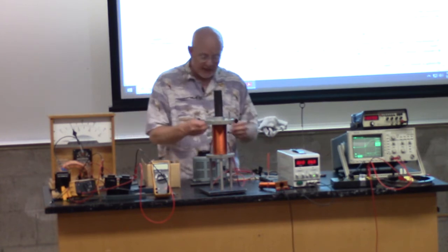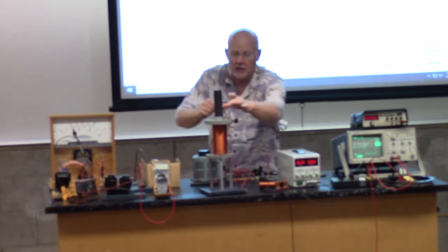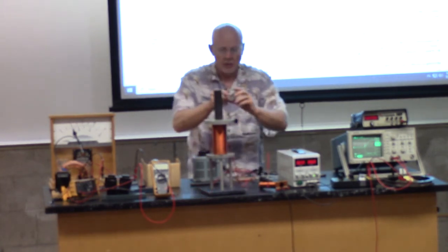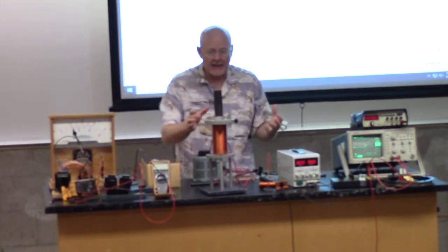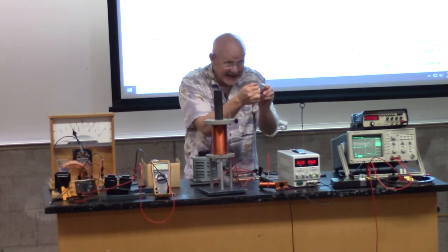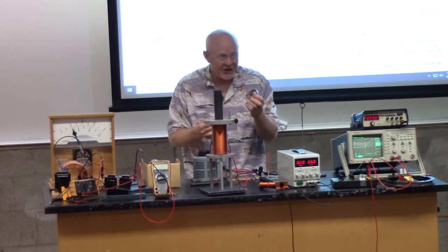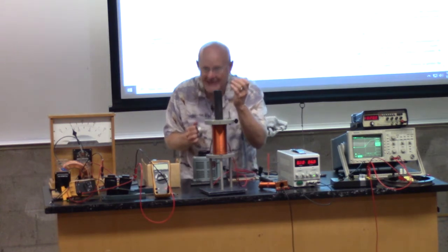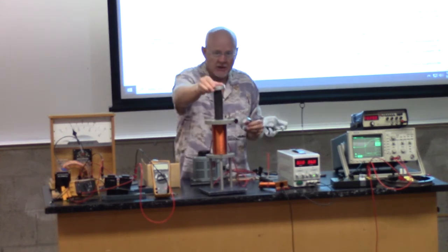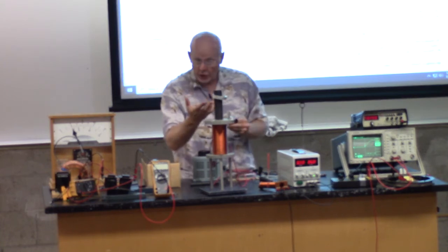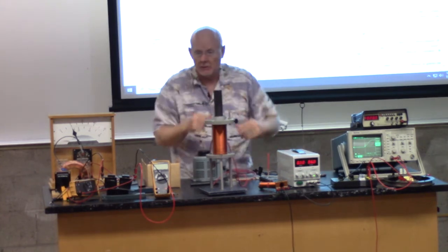It's best to see it with this one. This is that same kind of ring, but we cut it with a bandsaw. So this one can't get any current to go through it. It's been cut, so the secondary here can't have any current. And if it can't have any current, this one does not become a magnet. This one does become a magnet. Because it's a closed loop, it will get current in it and they will repel each other. But this one, because it's cut, doesn't get any current.